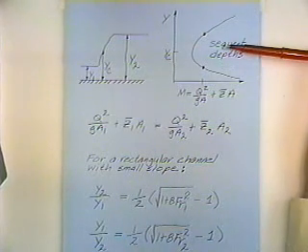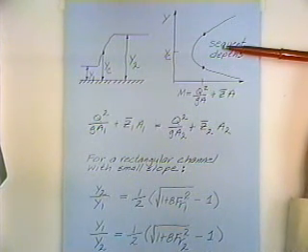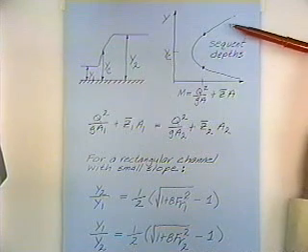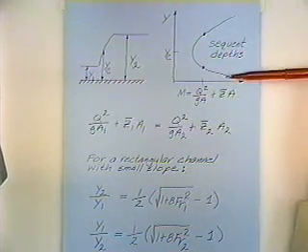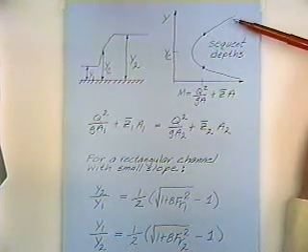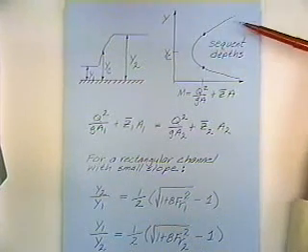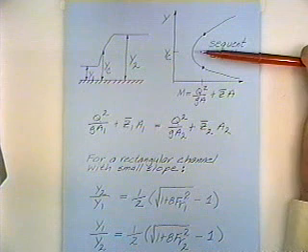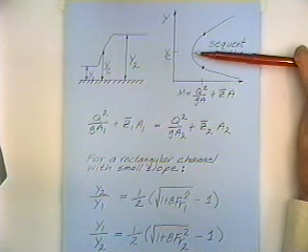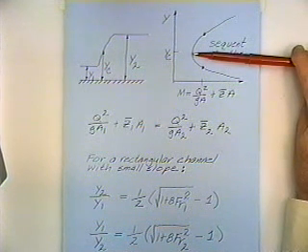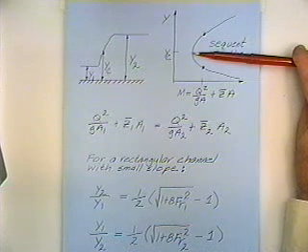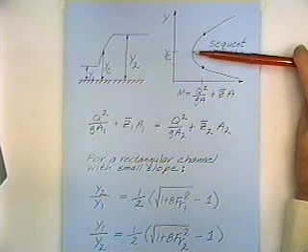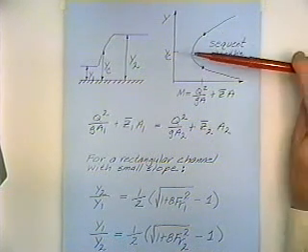Before, we looked at a diagram like this in which we were looking at specific energy, and momentum is sort of the same shape. The shape's a little bit different, but it's the same general analogous concept. The critical flow, by definition, is the condition in which the specific momentum is a minimum. Before, we said the specific energy is a minimum.